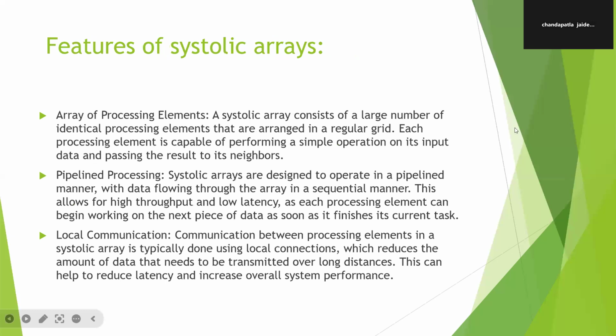Features of systolic array. Array of processing elements: a systolic array consists of a large number of identical processing elements that are arranged in a regular grid. Each processing element is capable of performing a simple operation on its input and passing the result to its neighbors. Pipelining processing: systolic arrays are designed to operate in a pipelined manner with data flowing through the array in a sequential manner. This allows for high throughput and low latency. Each processing element can begin working on the next piece of data as soon as it finishes its current task.